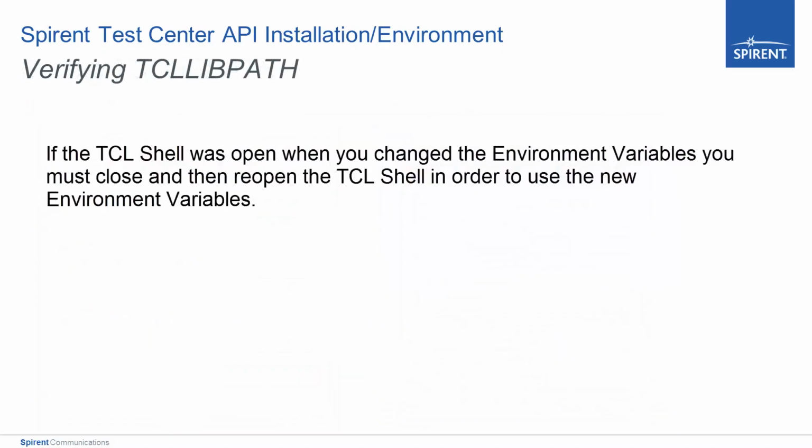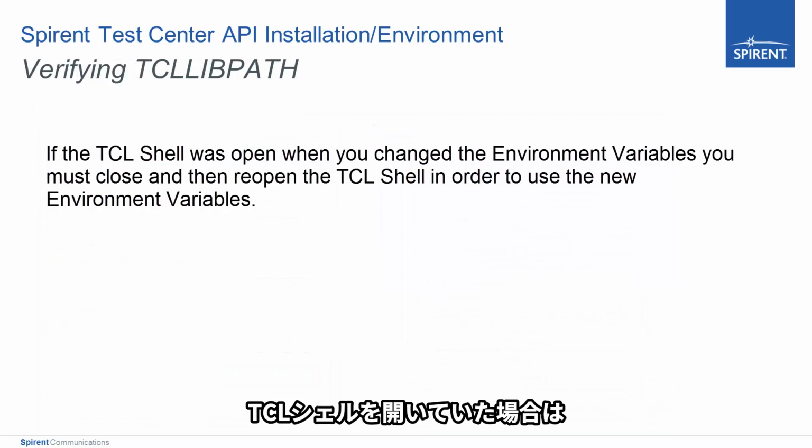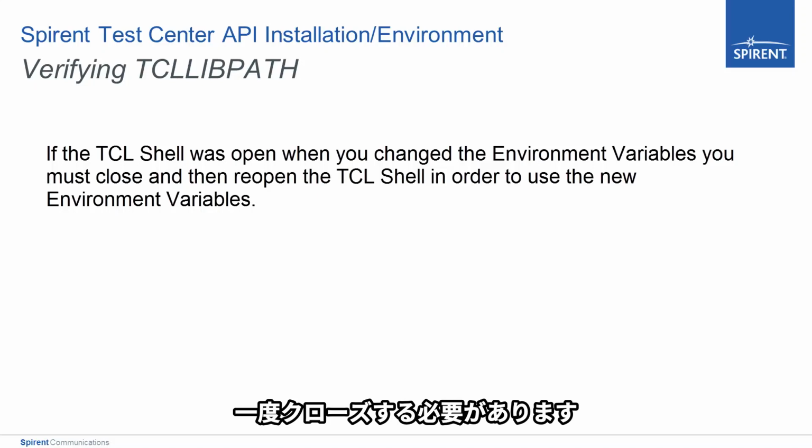If you had the TCL shell open, then you will have to exit the TCL shell as well as close the DOS command prompt. You want to refresh the TCL interpreter with the new values that you've changed within the TCLLIBPATH environment variable.